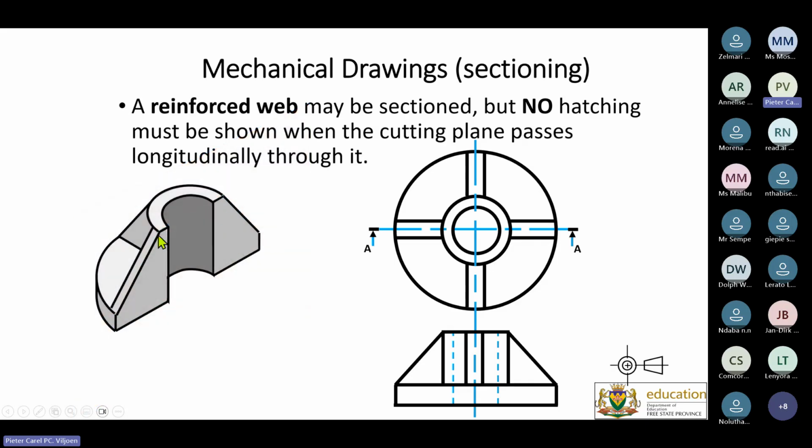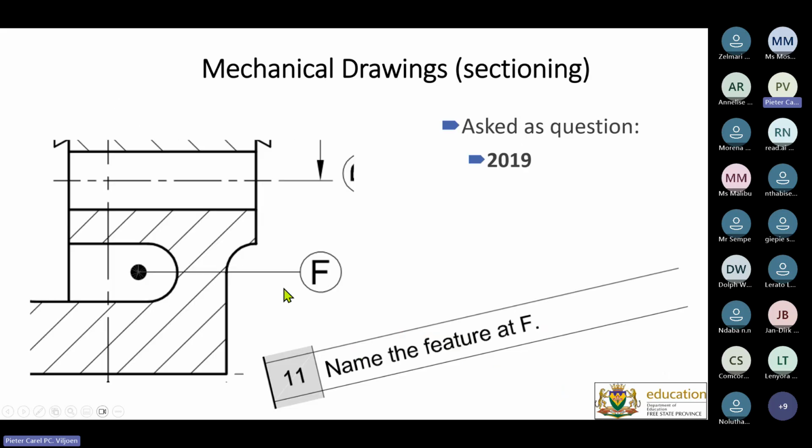Take your ribs off the drawing, and then from there on, you show this in this view over here. But just be careful because there are hidden detail lines at the front and at the back. There's a hidden detail line over here while it was still covered, but now it's been cut off. So therefore, these lines will become solid lines now. At the back there will also be hidden detail lines, and at the bottom there will be hidden detail lines. If you section it off there, it means there's no sectioning that is going to take place on either side over here. Hatching on that part.